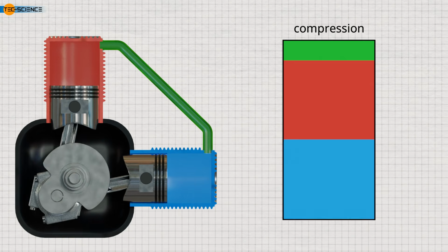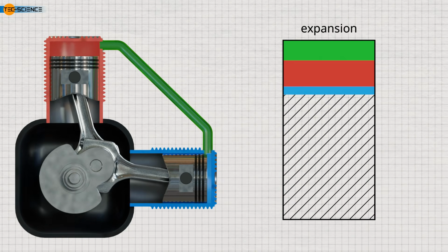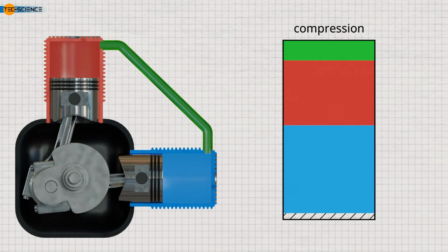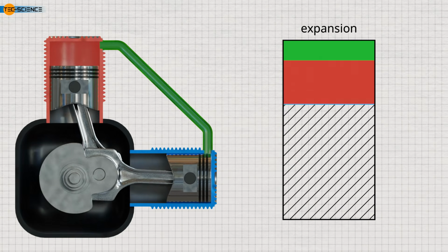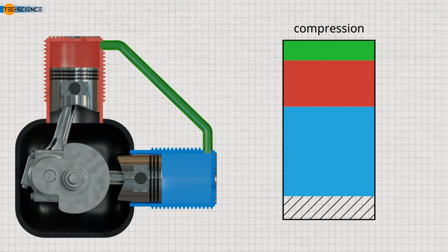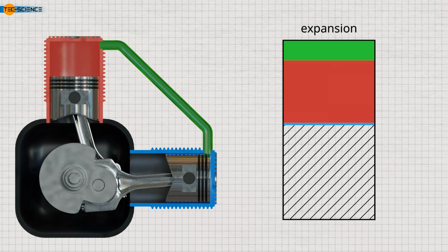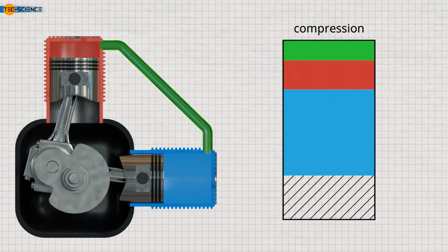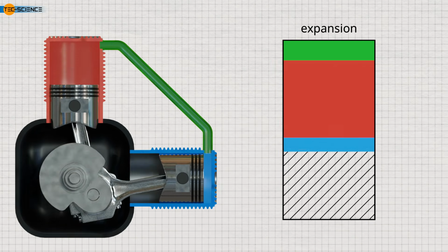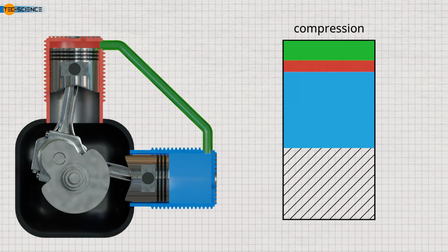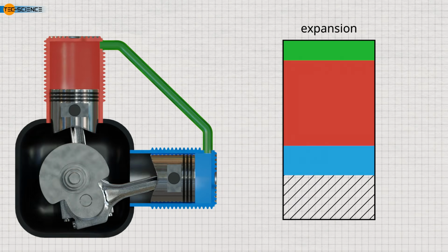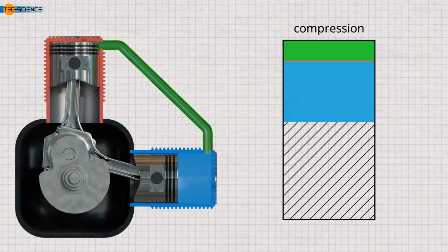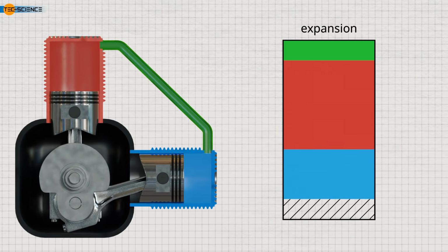Pressure is mainly determined by temperature. The higher the temperature of a gas in a closed system, the higher the pressure. When the gas expands, therefore, there must be more heated gas mass overall to exert greater pressure on the pistons. During compression, on the other hand, there must be more cooled gas mass in the cylinders so that the pressure on the pistons is lower. This is achieved by offsetting the cylinders by 90 degrees.